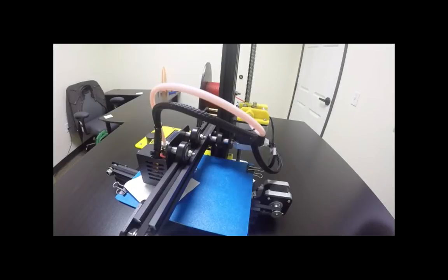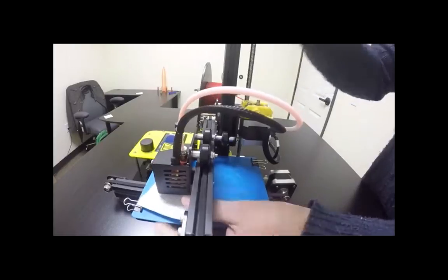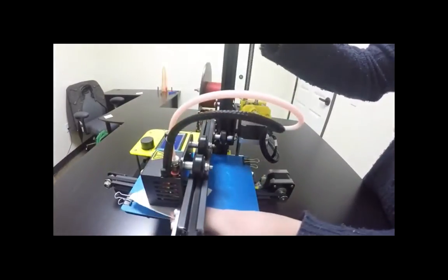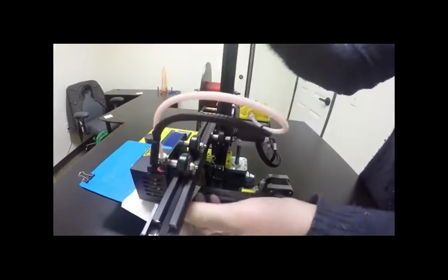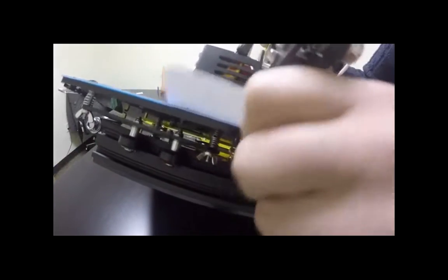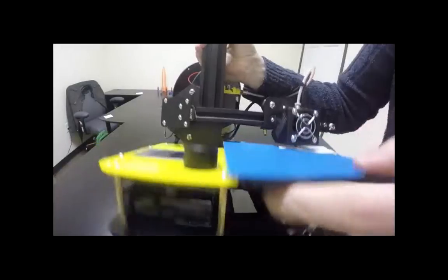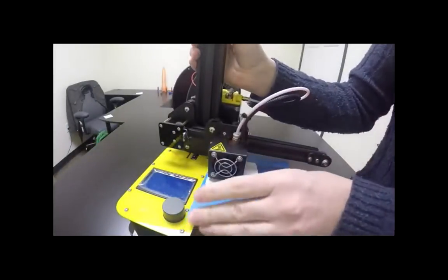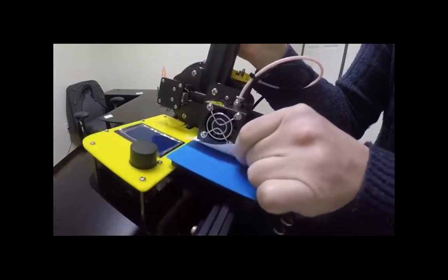Okay, we're good. And then when you move it, you can kind of feel it moving around a little bit when you're dragging it. And when you feel the paper dragging, then you'll move the blue plate over, and you'll do the same thing with this one and adjust this one a little bit to where you can move that one. And then you'll do the same thing on the one in the inside right here. So you'll move this over to here and then move this in the middle, and then you'll do the same test right here for this one too, to be able to move it back and forth.